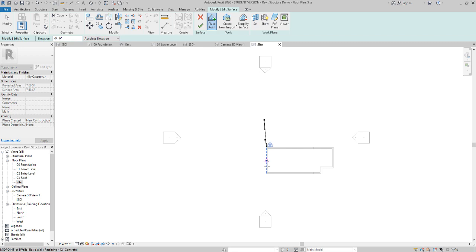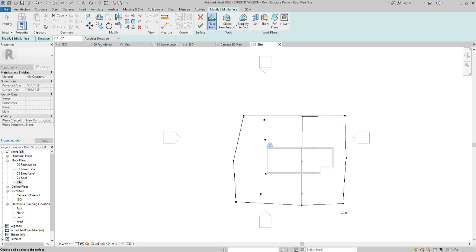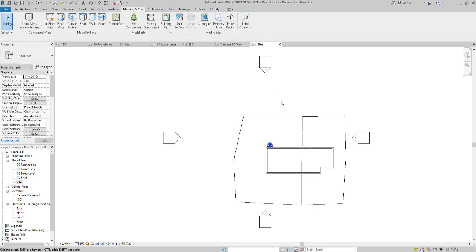Go and click through. I like to click just on the edge of this building here. Later it's going to make a difference that's about -6 inches. And then next we're going to be typing in -10 feet. This one we don't have to be so precise. We just click down the middle of the building. Then we're going to change that to -11 feet. So now the slope's getting a little bit less, and that becomes towards what I'm going to call the back side of the building, the lower side of the building. Hit the check mark on that.